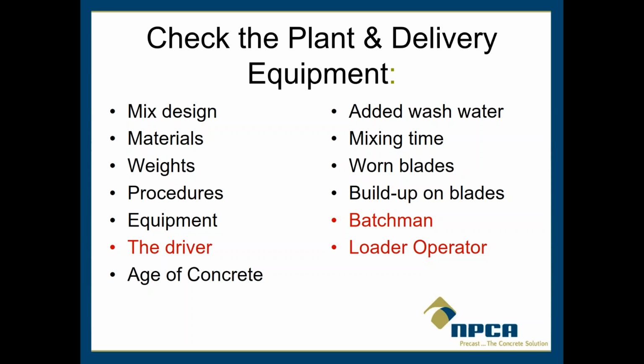Now, different plants use different delivery units. Some may use a tucker, some use ready mix trucks, some of it goes straight into the bucket. Whatever that delivery unit looks like, the guy who's delivering that concrete on a daily basis a lot of times has a lot of insight on what the concrete looks like. Did it look normal? I know normal is a bad word to use, but what did it look like? The age of the concrete: was it in the mixer longer than others? Did it sit in the tucker for a while? Did it sit in the truck for a while? All these things come into play.